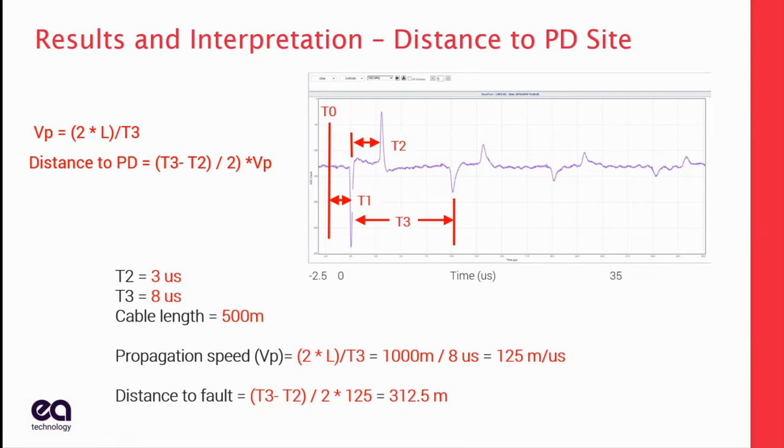If I look at my cable diagram, I may find a splice or I may find a termination. The idea of online testing is not to detect this all the time. It's to let you go through 20, 30, 40, 50 cables in a day, rule out 90% of them, like the Electricity Northwest example, and address the other 10%. At some point, I'm going to have to take action.